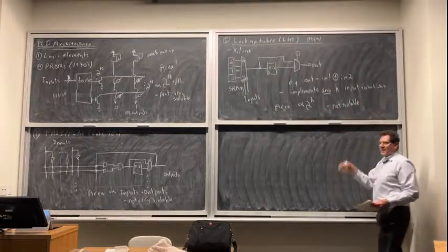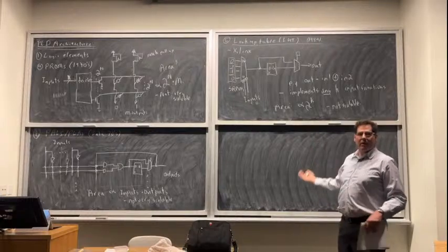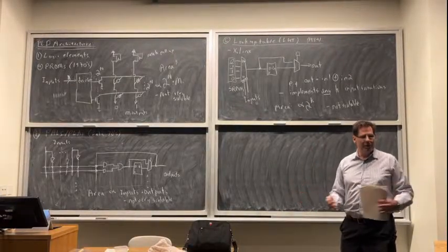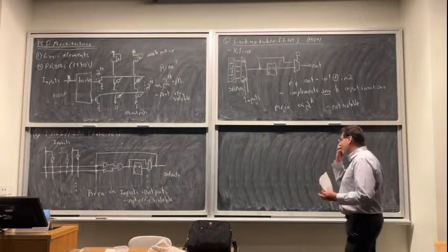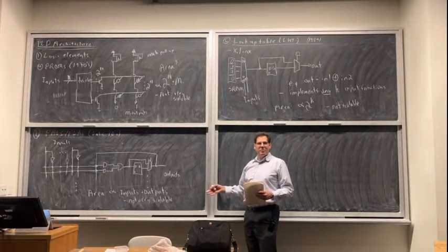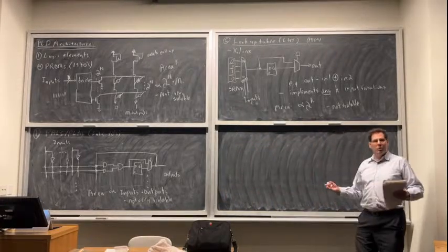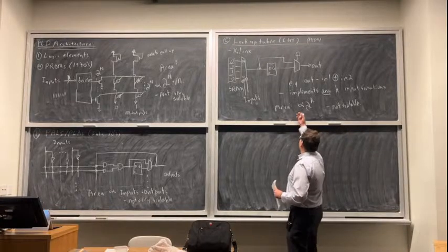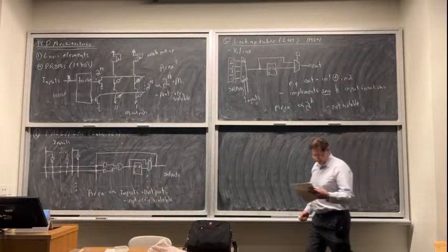So I'm saying not scalable, it doesn't mean bad. It's just one of the things you can think of: can I just make a logic element, and then as you get more and more transistors, you just make it bigger and bigger? And we're done, right? That's the best programmable logic you can get. So far, that's not true for any of these. They are reasonable as long as you keep your number of inputs and outputs reasonable, but if you make them grow sufficiently large, they become absurd. And this one becomes absurd faster than most. You can't make that number of inputs very big.